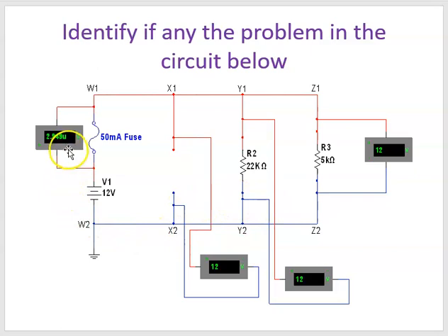All we can say is that the fuse is good, but either of these resistors or components could be open, and we cannot tell by these voltmeter readings.